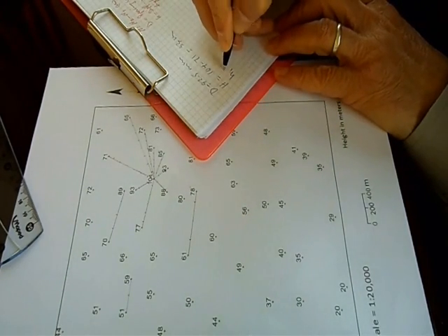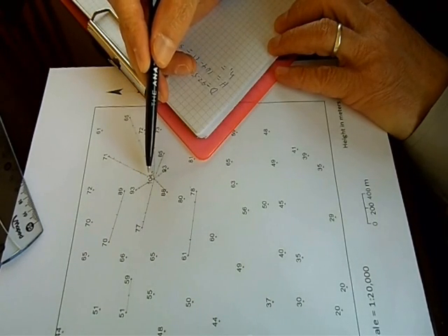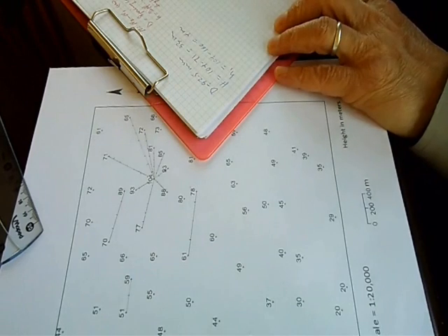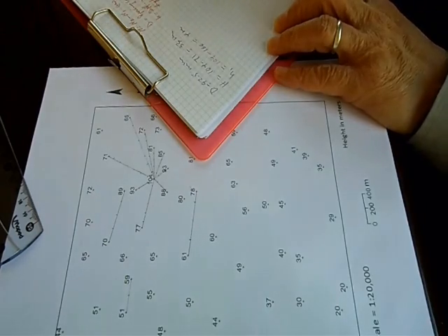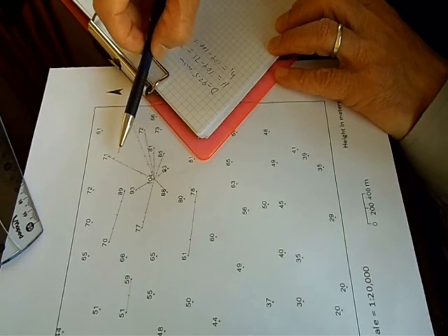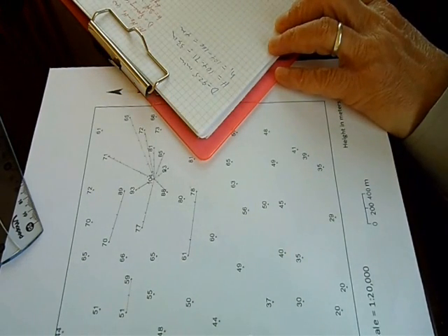Small h1, which is the difference between this point and the first preceding contour line, which is 100, is 104 minus 100, and that is 4 meters. Now the contour lines that we expect to pass between these points are the 95, 90, 85, 80, 75, and finally the major point 71.